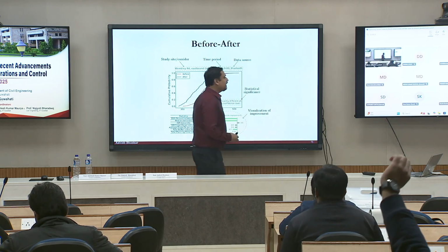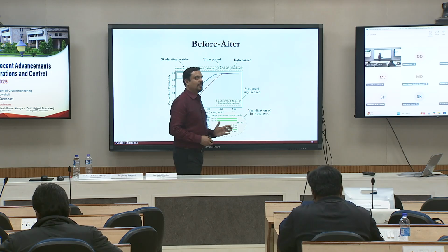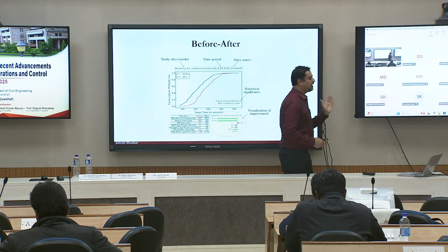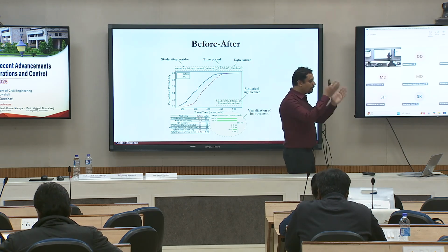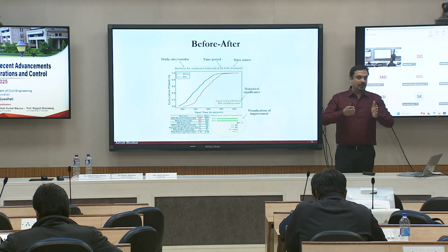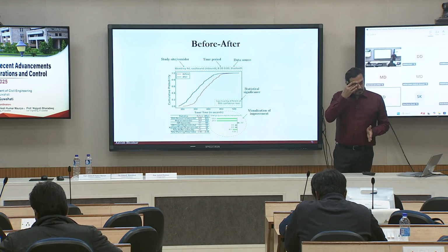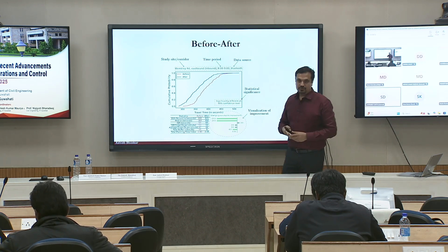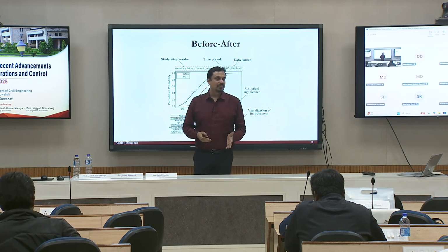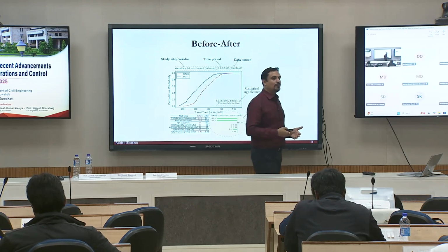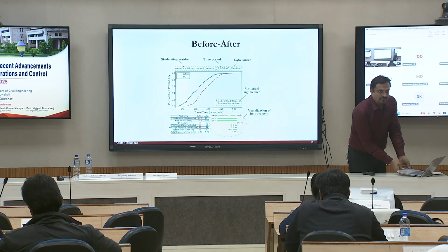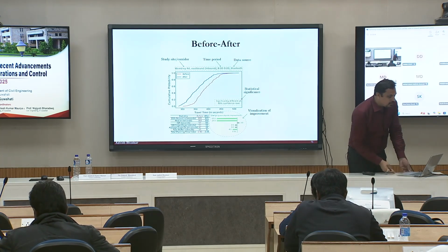Now the other thing is the slope of the plot. If the slope is very steep, it means that most of the data points are concentrated around one value, right? Yes. You're talking about the central tendency. Yes, sir. If the slope is steep, I have less deviation. It means that a steeper slope is giving me more confidence in my travel time, so my reliability is better. Yes. Now that's the only concept which is there.